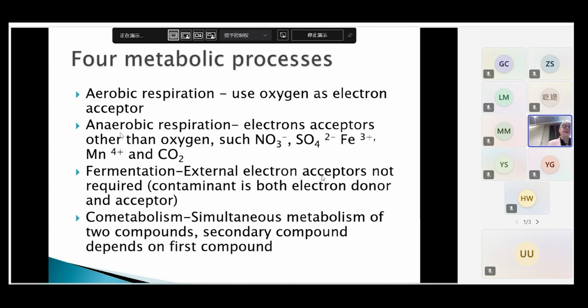Basically how it goes, you could do a multi-step process something like this: remove the uncontaminated, oversized materials, do the treatment in the reactor, and then you have to separate the soil and the water. And hopefully you'll have some nice, clean, decontaminated soil at the end of the process. So obviously it works well. You can have very good mixing, you can supply the oxygen very well, and you could even degrade some contaminants that are a little bit more difficult to degrade.